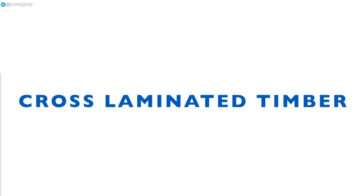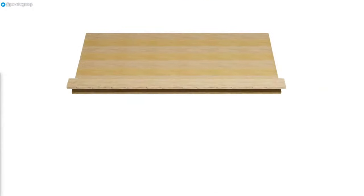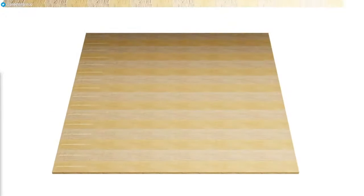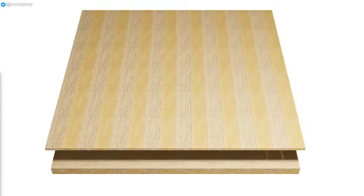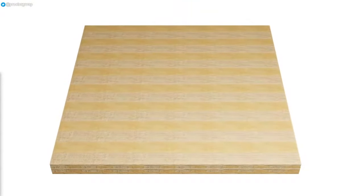In a cross-laminated timber panel, softwood timber planks, typically 30 to 40 mm thick, are glued together to form solid panels. An odd number of layers are glued together at right angles to each other and bonded together under pressure to form solid structural timber panels, similar to large, thick sheets of plywood.